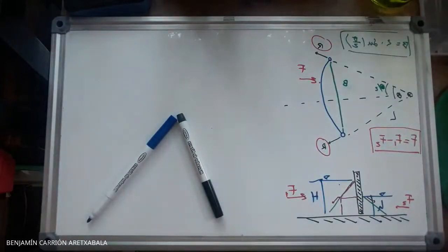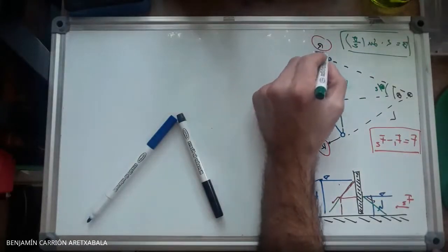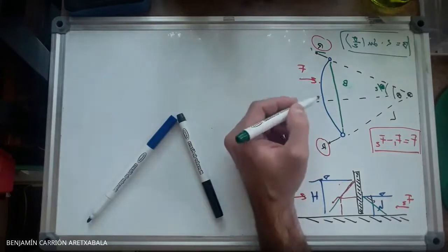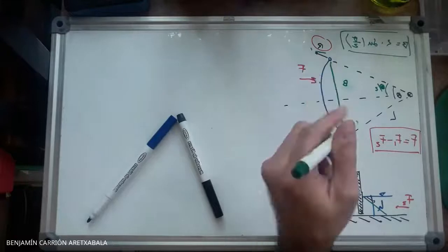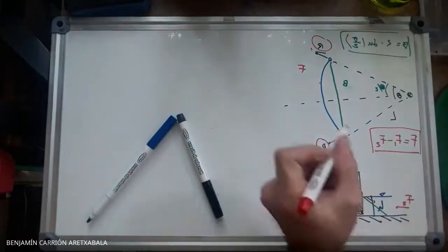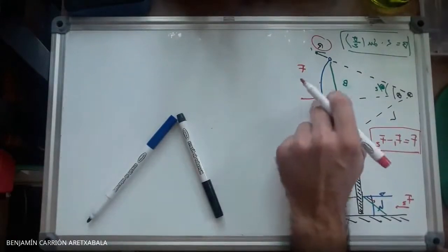And the other thing you could have seen directly is that you could project these resultant forces R into this horizontal plane. This is a symmetric problem. So you didn't have to argue actually that F was going to act in the symmetry plane.